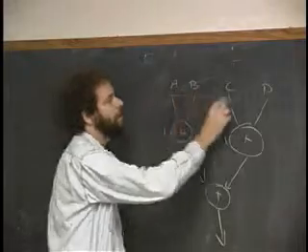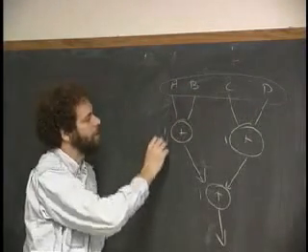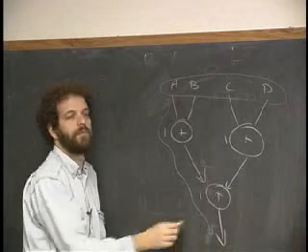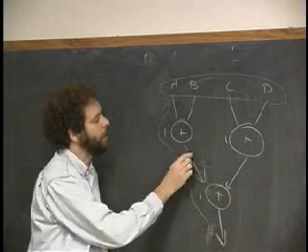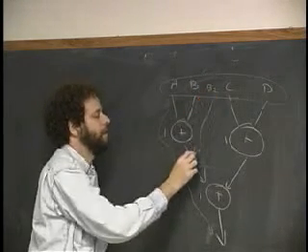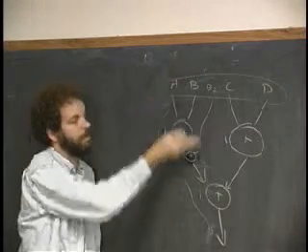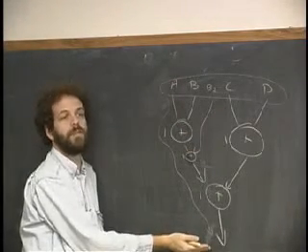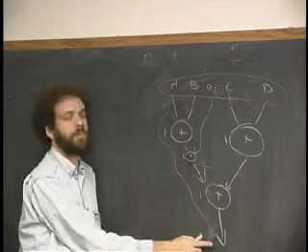If I present all this data at the same time, it's the maximum propagation delay along any path from the beginning to the end. So, for example, if there was a third adder in here that was adding B2 in, and this had a 1, then the latency of the whole circuit would be what? 3, even though there was a sneak path here, which was 2.